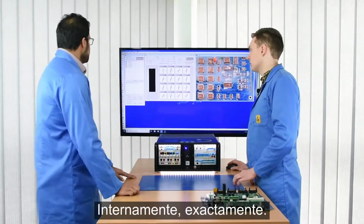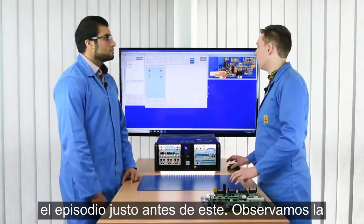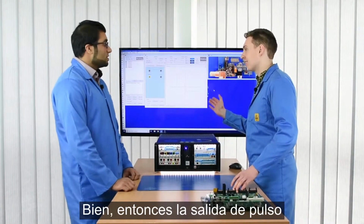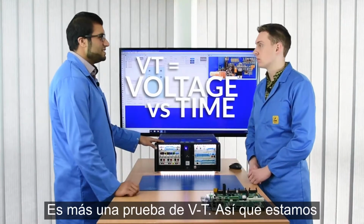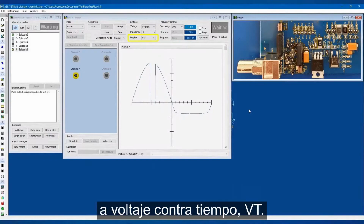Internally, exactly. So episode 6, the episode just before this one, we looked at pulse output using the 3D VI. Can you tell me, is this a VI test? Okay, so the pulse output is a slightly different test. It's not a VI test, but it comes as part of the BoardMaster. It's more of a VT test. So we're changing the display from voltage against current to voltage against time, VT.